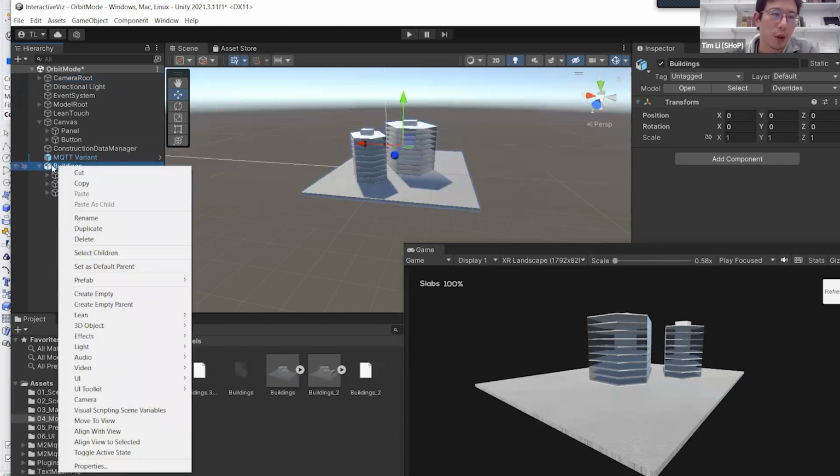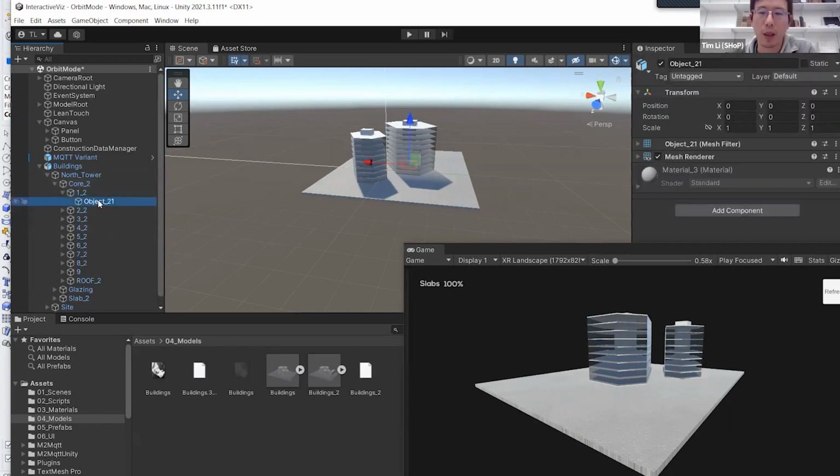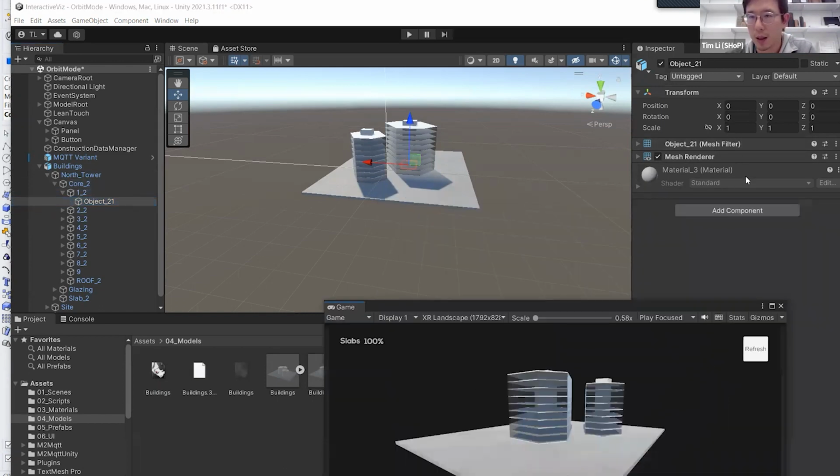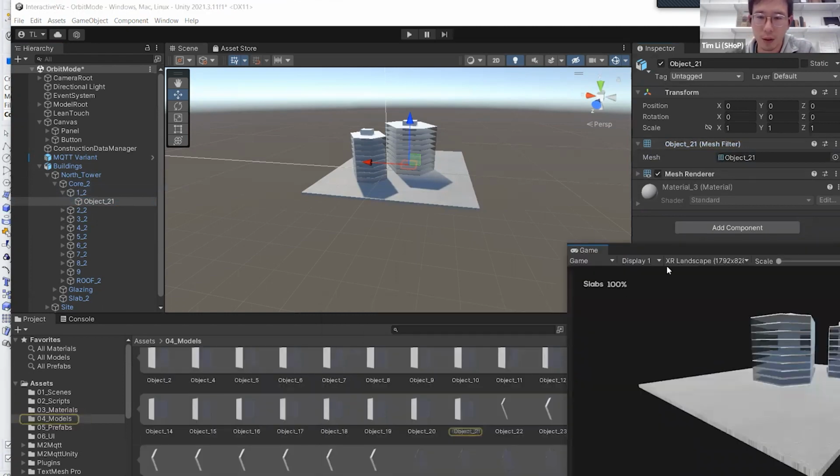So there's a way to break that link, which is if you right click on that model and then do unpack, it'll break the link. Maybe that works for your workflow where you want to keep different versions of the same thing. So even if you override to the same, actually, that's not true. If you expand all the way to the most basic unit, it has a link to the geometry inside the file.